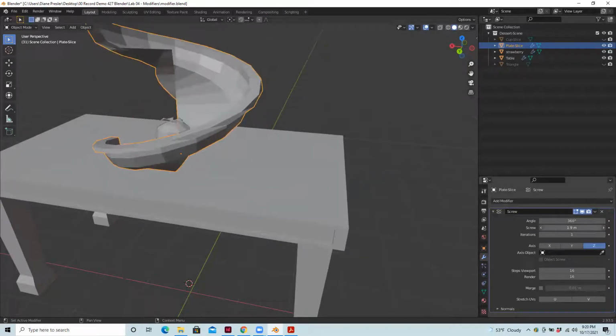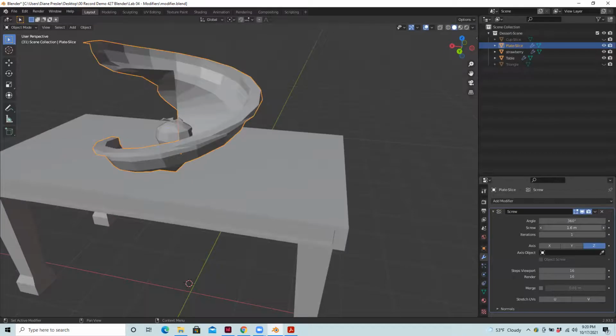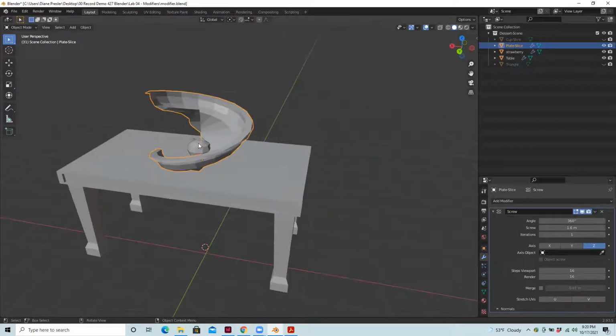It's funny, pictures really explain things. If you set a screw value, it's twisting up, almost like a spiral stairway or shell that's twisting. So if we do want it to remain level and not change elevation at all as it moves around the circle, then I can take the screw value back to 0. And just keep thinking, how can you use these features in your project?